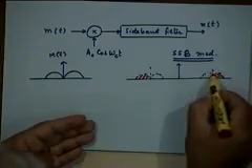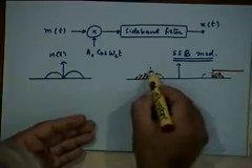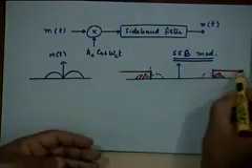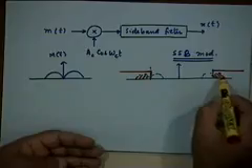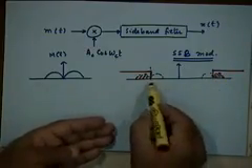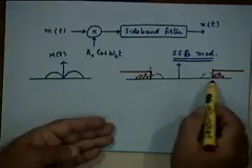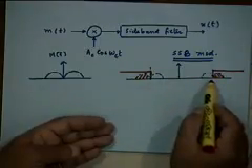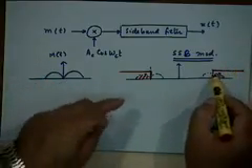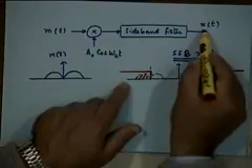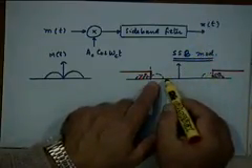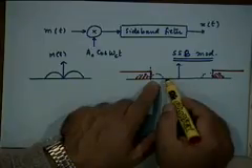So you require a filter with this kind of characteristic, whose transfer function is 1 for |f| greater than fc and is 0 between minus fc and plus fc. Is it clear? For |f| greater than fc, the transfer function is 1, so it will pass this spectrum to the output, and this spectrum will get attenuated or suppressed, eliminated, right?